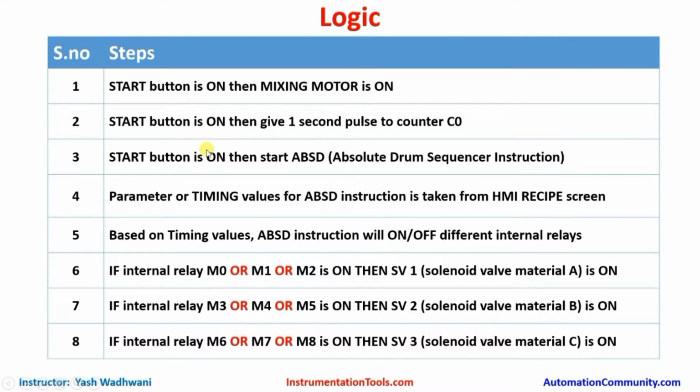And what is the third thing? As soon as the start button is pressed, this instruction should be started. This is the main instruction of our project. Its name is ABSD, Absolute Drum Sequencer Instruction. In the previous traffic light project, we used the INCD instruction, which is Incremental Drum Sequence Instruction, and here we have used the Absolute Drum Sequence Instruction.